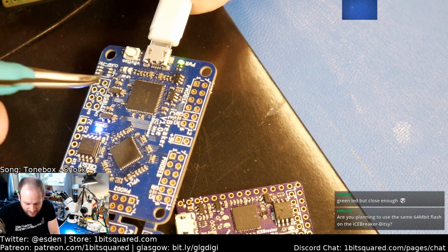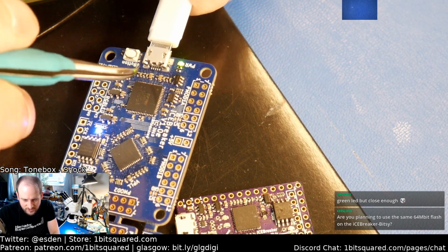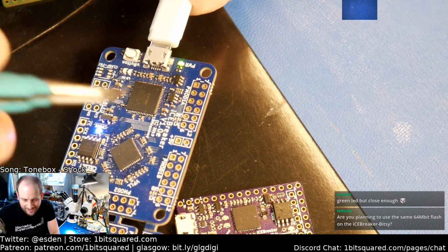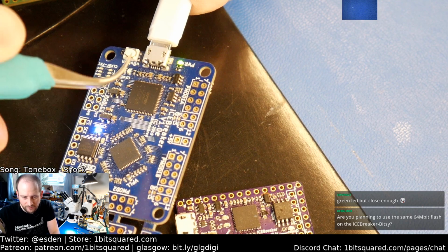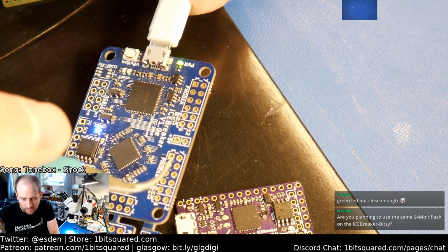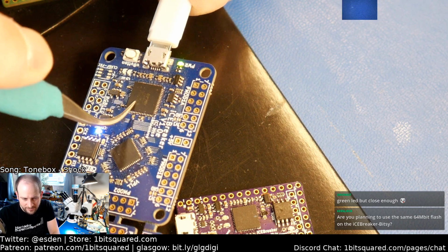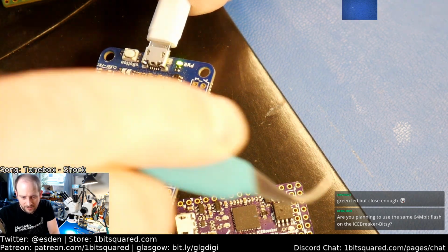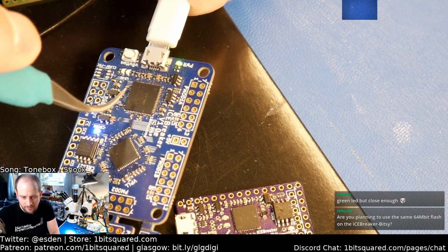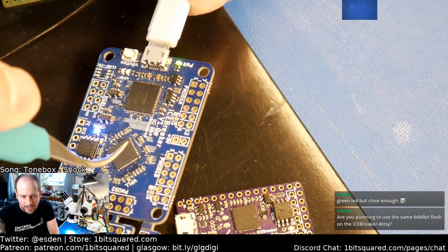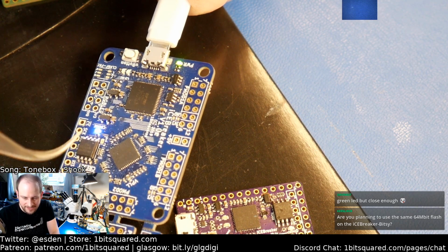So the aux chip select from the FTDI chip can be used to connect to the FPGA and then stream data over SPI, which is faster than UART, into the FPGA. This is how we are doing video streaming to LED panels through the iCEBreaker. So you take USB, SPI, FPGA to the LED panel, and we use the auxiliary chip select line from the FTDI chip to do that on the same pins that the flash chip is located on. So that's the idea.